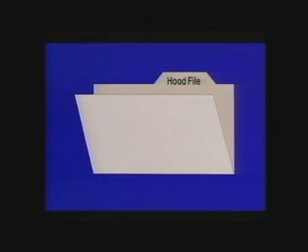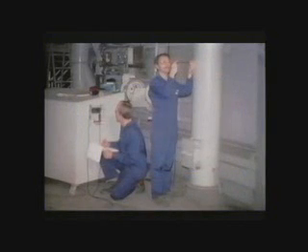All ventilation systems require maintenance. A good maintenance program consists of, first, a written program; second, a good record-keeping system to store drawings, plans, specifications, modifications, operating instructions, monitoring and testing results, and so forth. Third, a good program provides for regular testing and inspection of the system. Checklists can help. One is provided in the handout materials included with this program.